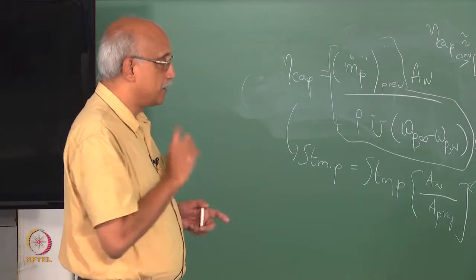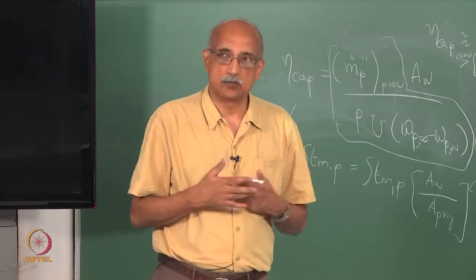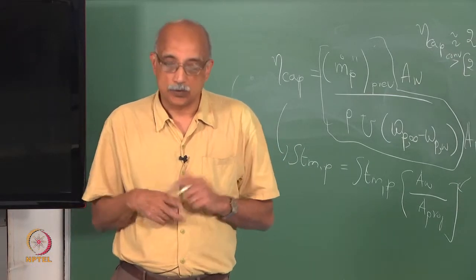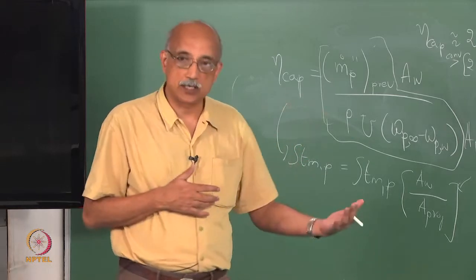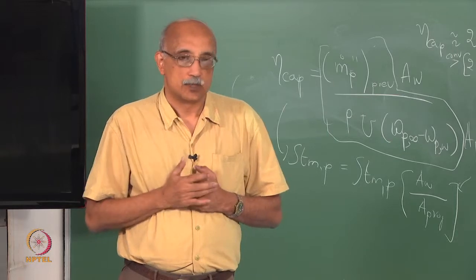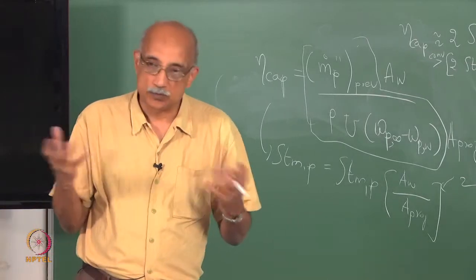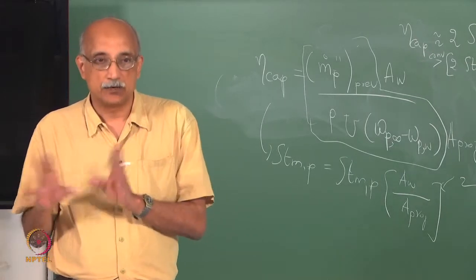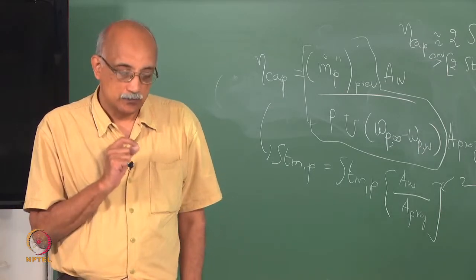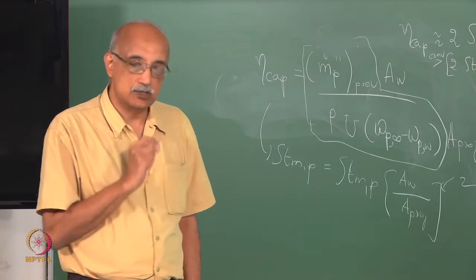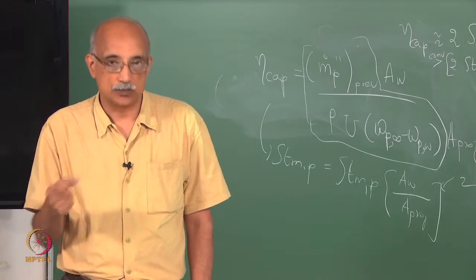To measure these parameters, Reynolds number is easy to measure. You probably have done some experiments in the momentum transfer lab, or I think you are going to do next semester, to look at Reynolds number measurement. But Schmidt number and therefore Nusselt number, Stanton number are actually very difficult to measure, because we are talking about measuring mass fractions of compounds, particles, which are typically in the parts per million range, sometimes in the parts per billion range. So, these are extremely small values, and it's very difficult to develop instrumentation that can measure such small mass fractions with sufficient accuracy and precision and so on.